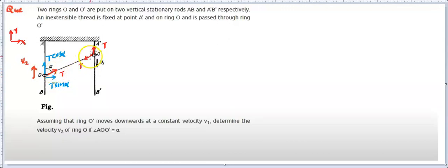Moreover, if you see, this angle is also going to be alpha, alternate angle, right? And this will make two components of this tension, one in the horizontal direction, another in the vertical direction. This horizontal component will come as T cos alpha, and this will come as T sin alpha. So what I am doing is, I have drawn these tensions and made the components so that these tensions can be written in terms of vectors. Now let's say this is 1, so that's why we are calling it v1, and another one is 2, so that we are calling v2, right?